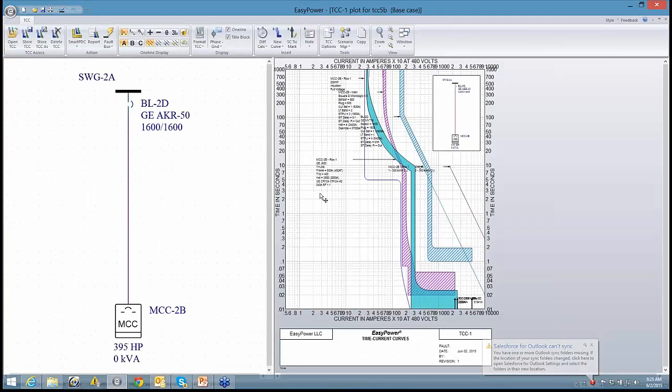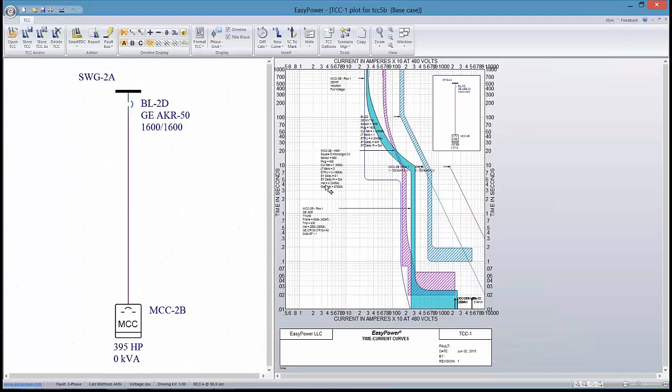And so what we have here is the breaker that's actually probably upstream of the load. Here is the load that's within the panel, and for right now what we really want to see is, it looks like this is a molded case circuit breaker, and it's probably set up as well as it can be. But again, this is downstream from the main breaker, so we're really not concerned about this in terms of the arc flash protection.